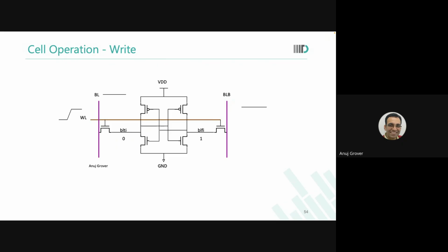You are assuming I will put an inverter between them. I will not. I will drive both bitline and bitline bar with a different independent logic. I can do that, na? Where was the inverter needed? Between D and D bar. I never said inverter is needed between B and B bar. I just called them bitline and bitline bar. Just by calling something something, you do not give it the functionality.